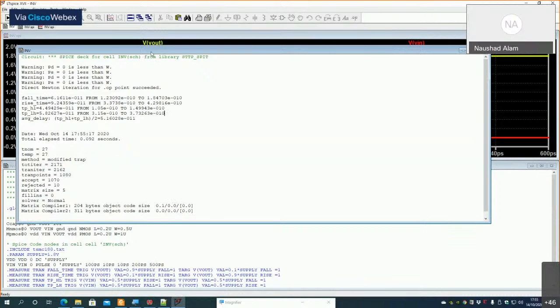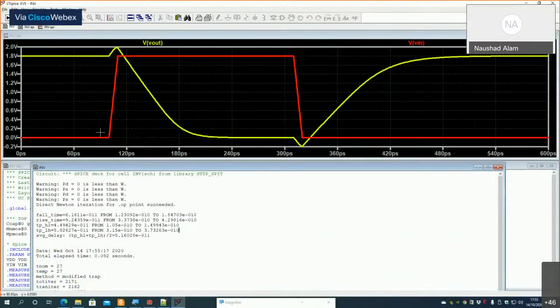Now you can see that for measuring leakage power, for an inverter, you have leakage power for two cases: when the input is 0 and when the input is 1. So you have a leakage current flowing and that results in leakage power. For dynamic power, you have two situations: when the output is switching from high to low and when the output is switching from low to high.